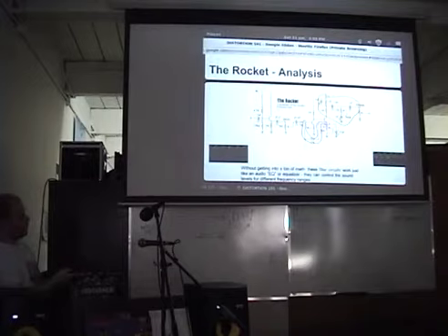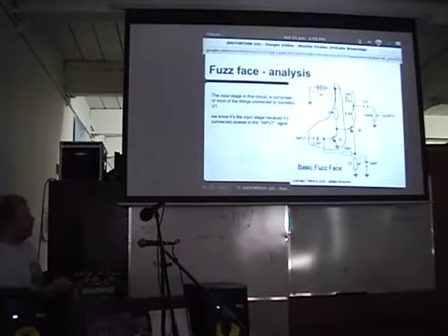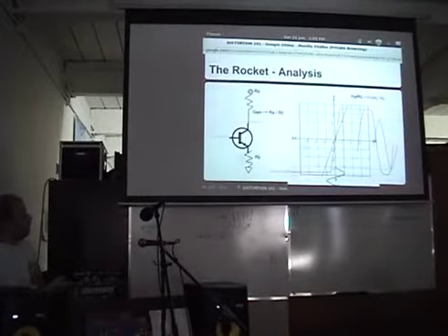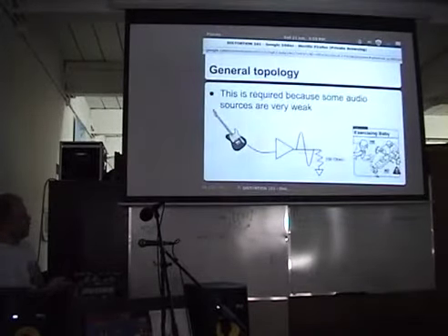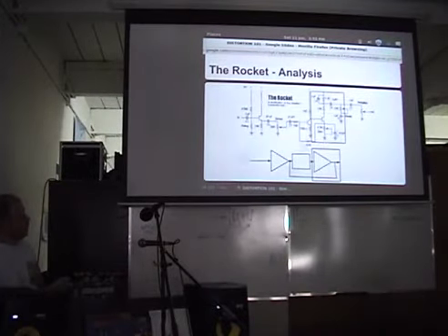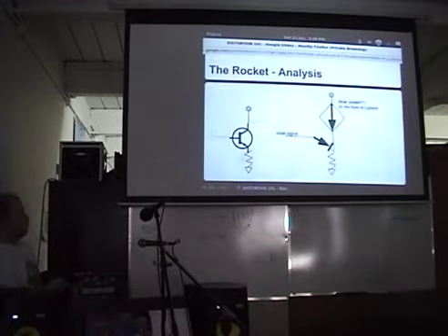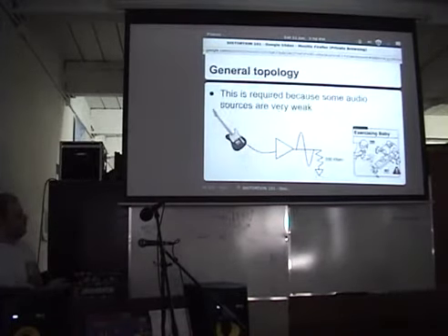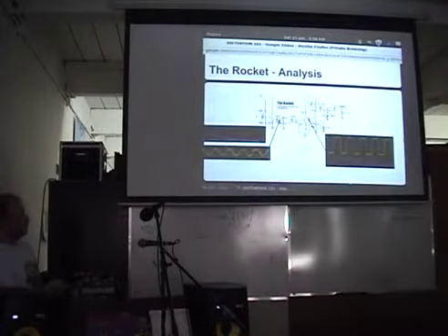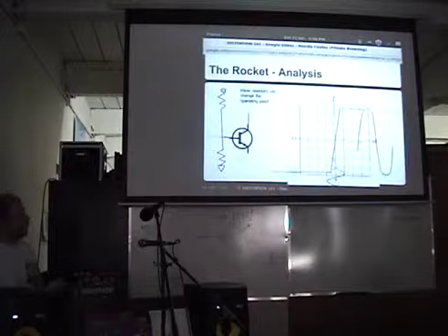You can see it's taking some voltage from this transistor and feeding it back to the input stage here. If you recall from the diagram, I did have a line, although I haven't practiced this enough to remember where that diagram is. Yep, there we go. So we see this line coming from the output here and back to the input here, which is usually used to limit the amount of gain in some very specific and fast ways. Back to where I was here.